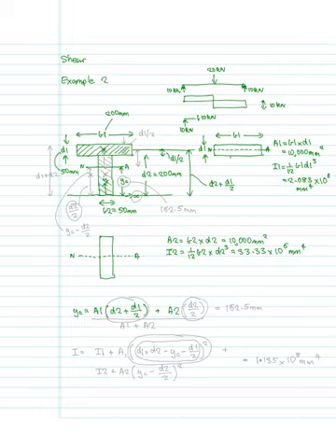So I'll put another shape there. So that's going to be our area 2, and the centroid of area 2 must be acting there, and the centroid must be a distance D2 over 2 from the bottom face. So it's going to be A2 times D2 over 2.